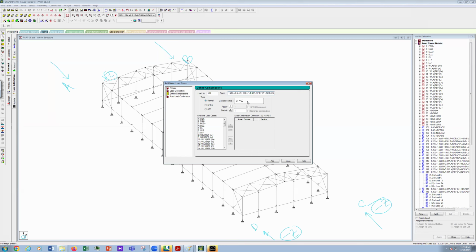Okay, so again we'll start from transverse direction and point A again, X direction. Okay, which reference point A, we will start from positive A. For positive, you can see this is N dead X. Okay, so N live. Okay, positive, and there will be another one because in earlier combination there was no floor live load. Okay, but this combination we have floor live load, so we will now add this. So what will be added?